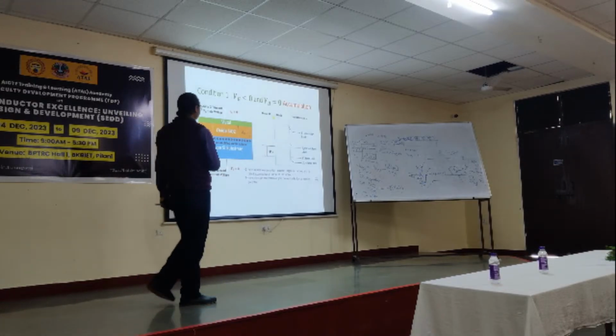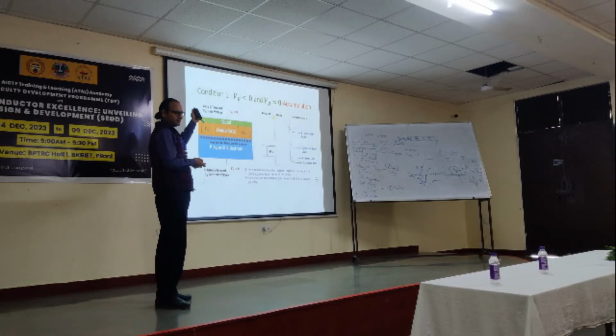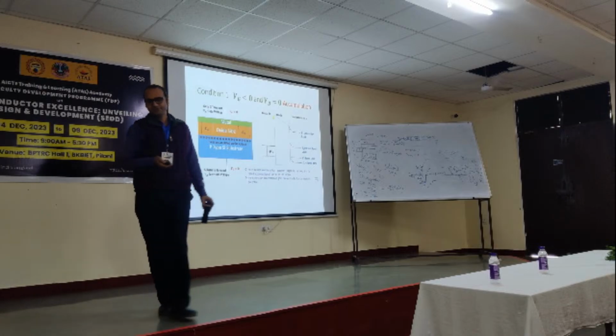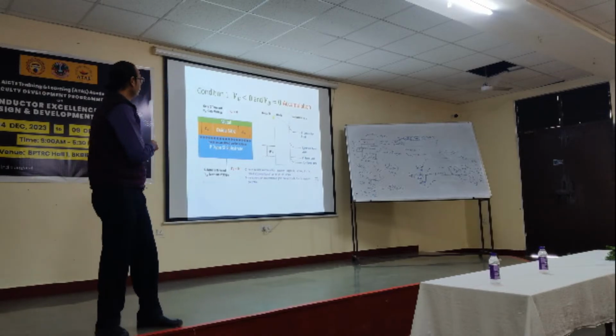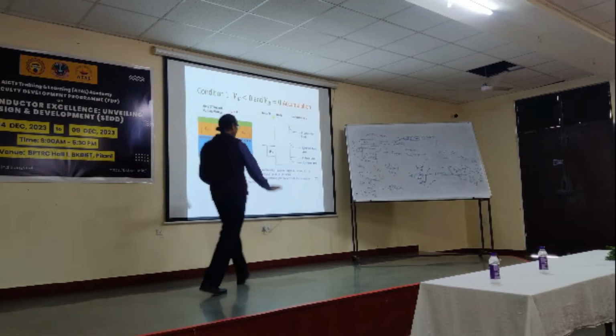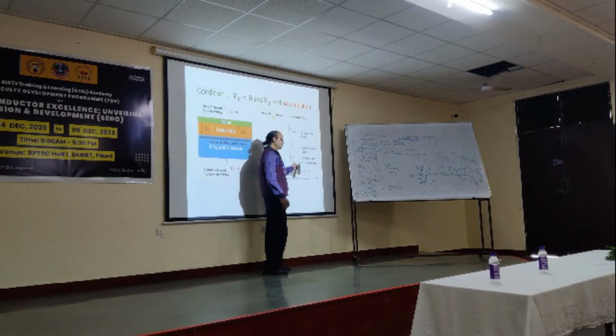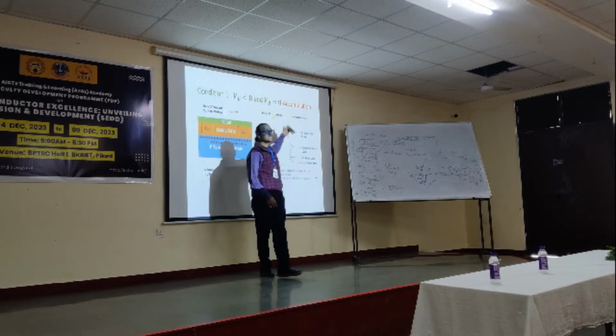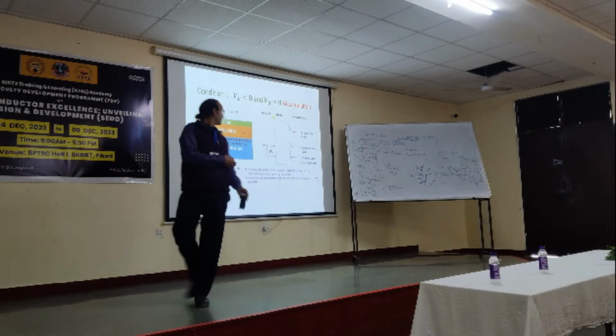so now I'm discussing one by one, the accumulation, depletion and inversion. So the first situation is accumulation. Accumulation means the valence band getting closer to the Fermi level, even in a p-type semiconductor. So the accumulation band diagram should be like this, right?